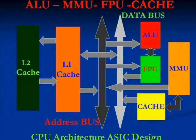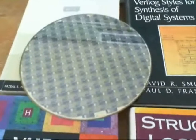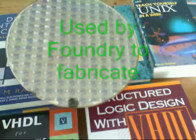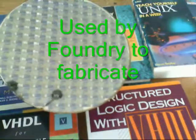Finally, the file produced at the output of the layout is the GDS2 file, which is the file used by the foundry to fabricate the silicon. The layout should be done according to foundry design rules.